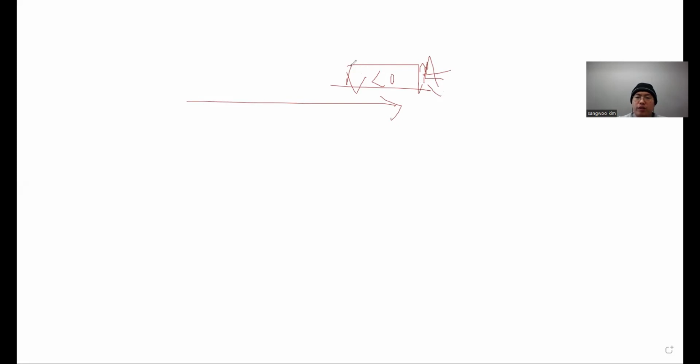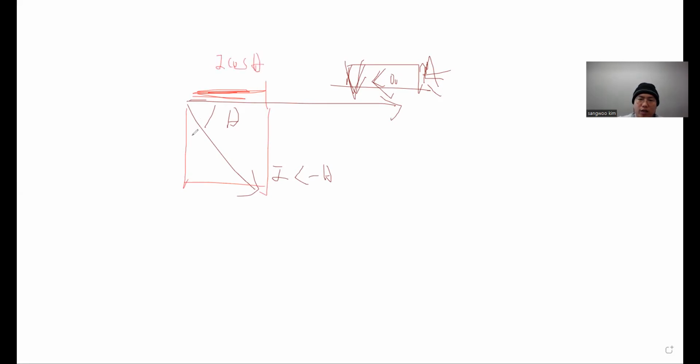Since we use a voltage system, the reference is voltage, and our general load in power systems is a little bit lagging, like this. So the current is I at angle minus theta. This part is I cosine theta. This part is I sine theta, right?